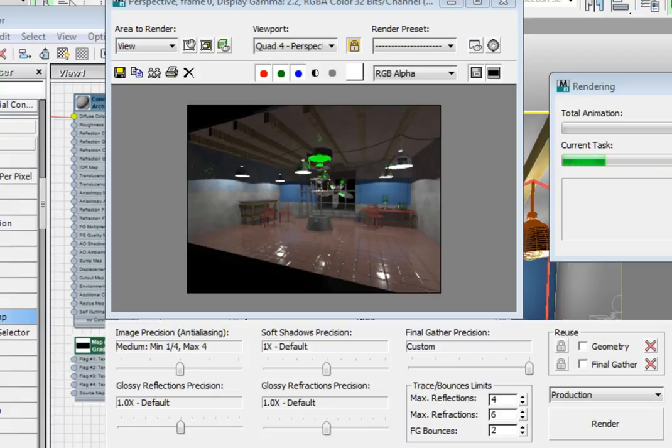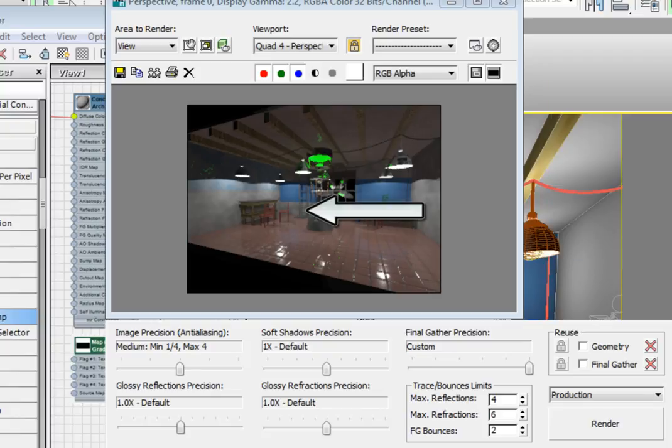If we look at the rendering, we can see that we have a lower band of concrete, a middle band of blue paint, and an upper band of concrete, all based on the pattern we've created using this gradient ramp. This method is very flexible and efficient, and it does not depend on the geometry of the object. Press Ctrl+S to save the file.